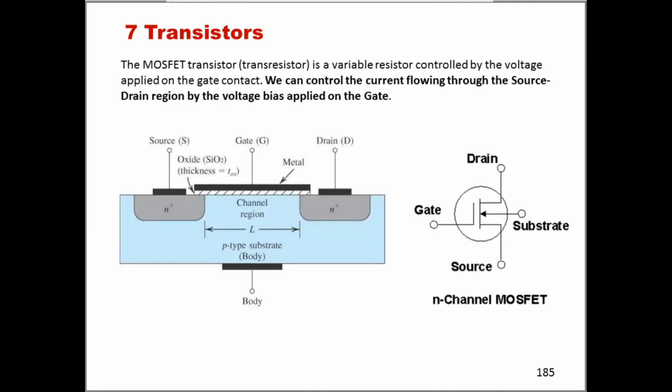So we've seen the schematic of a MOSFET at the very beginning of this course. Here we have this schematic again in front of us, a cross-section of a typical MOSFET. So we can see that we have source and drain regions that are N-type doped, and then the body, the substrate, is a P-type. And the region in between is the region that we've identified as the channel, where any current will be passing through.